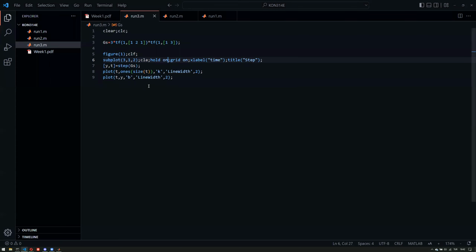Now, if we look close to the step function and what it is good for, we have to remember the Laplace transform again. We have to remember that step type inputs, if you look at the Laplace table, are basically modeled with 1 divided by s. So yeah, and we have the system. Let's say we have GS. What y actually is equal to is GS divided by s, if you're looking at a step response.